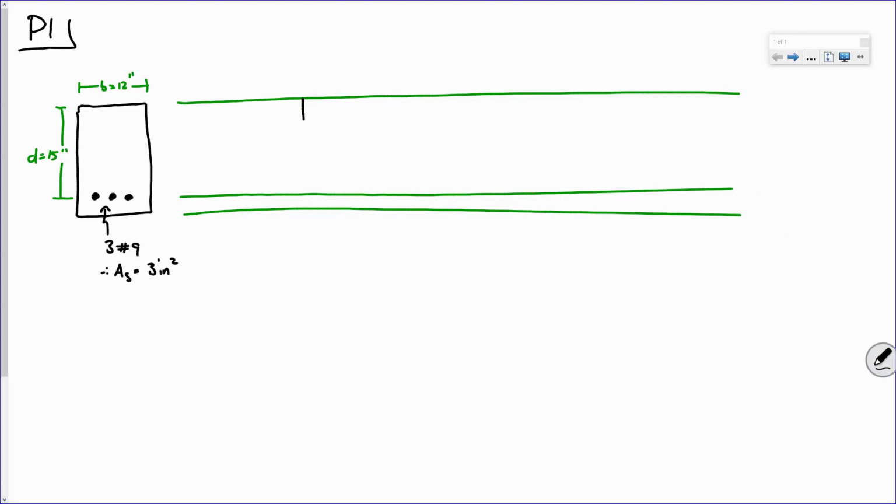So if you remember, the strain profile is going to look something about, I don't know, like that. Remember that? And so this strain is what? Epsilon sub s, the strain in the steel, right? Let's do some dimensions. This dimension, if you recall, anybody remember what that is? That's C. Exactly right. That, remember, from the top of the beam to the point where there's no strain, that's